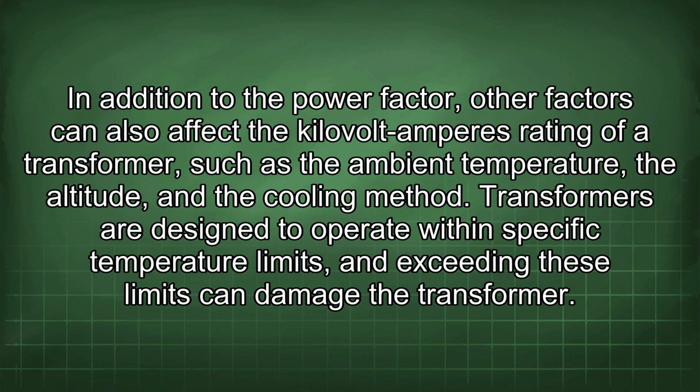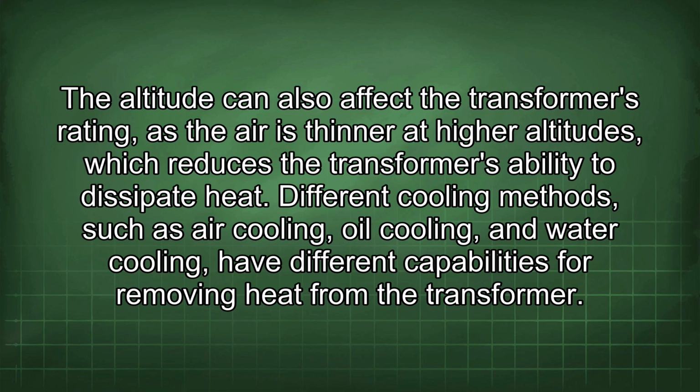In addition to the power factor, other factors can also affect the kilovolt-amperes rating of a transformer, such as the ambient temperature, the altitude, and the cooling method. Transformers are designed to operate within specific temperature limits, and exceeding these limits can damage the transformer. The altitude can also affect the transformer's rating, as the air is thinner at higher altitudes, which reduces the transformer's ability to dissipate heat. Different cooling methods, such as air cooling, oil cooling, and water cooling, have different capabilities for removing heat from the transformer.